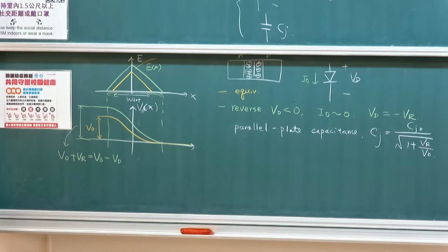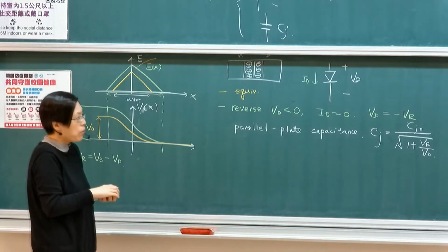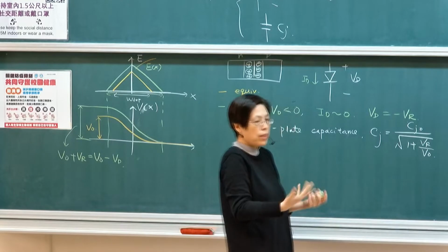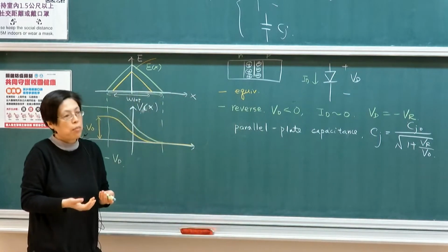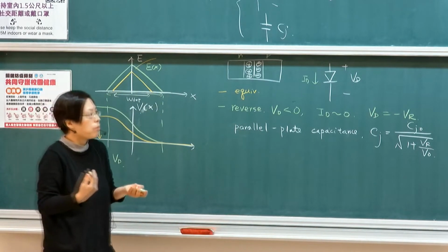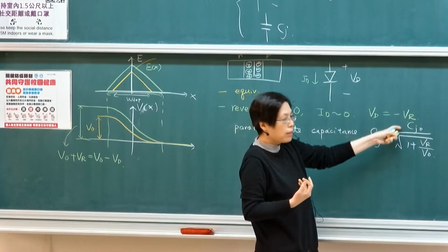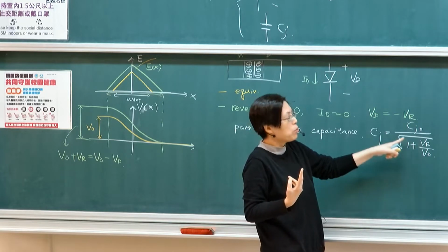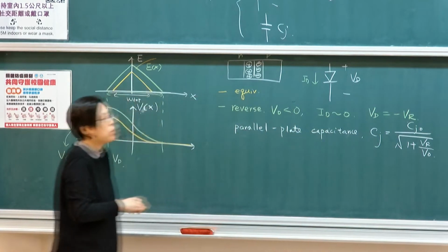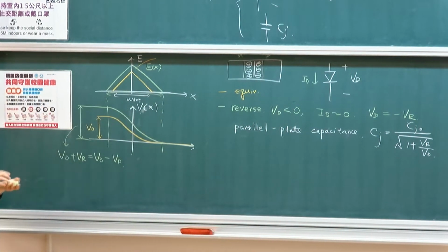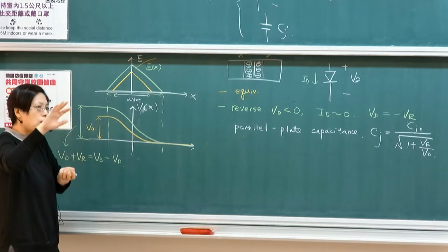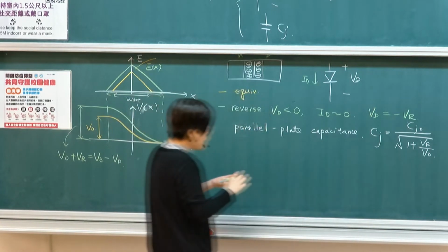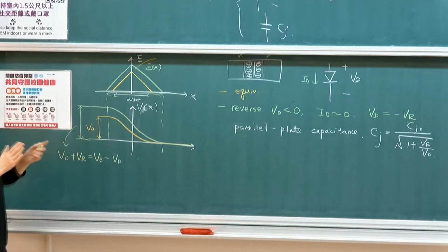That simply means that if I'm applying a reverse bias voltage, let's say 3 times as high as V0, for example, if V0 is 0.7, I'm applying minus 2.1 volts, I would then reduce my capacitance by 2-fold. So if this is 3 times, you would expect the capacitance to drop by 2-fold. You can do a simple calculation to get a sense of how the capacitance changes because the depletion region widens.